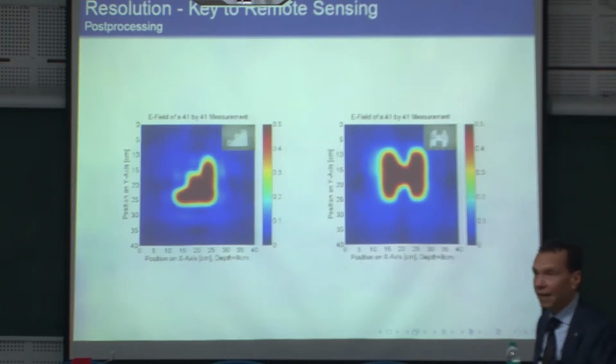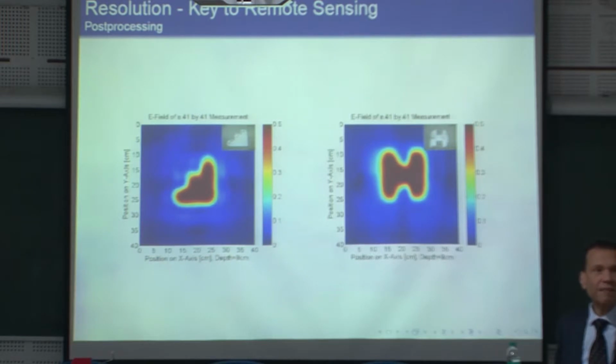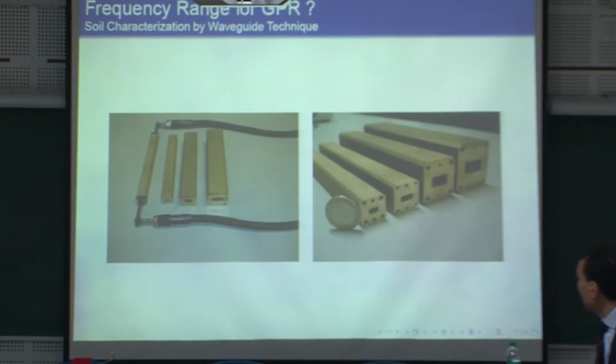But the other effect here, the two-dimensional, if we focus exactly at the surface, nevertheless, we will not have the exact image. We will have the effect of the point spread function. In optics this is called blurring. So it is smeared out. The synthetic aperture radar itself is you go with the antenna 40 centimeter in each direction. I will show you now the setup, how it looks.